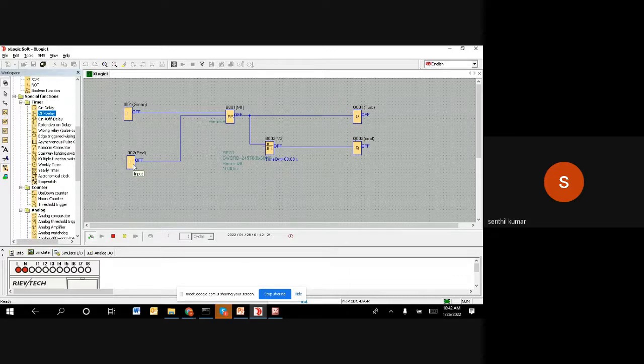Anytime you start the turbine, the cooling system has to go on immediately, whereas when we switch it off, the turbine has to go off immediately, whereas the cooling system has to run for the next predefined time. Based on the design, it can be half an hour, 1 hour, or 2 hours, based on the volume of cooling media required. So that's what it does. You understood some basic knowledge of what this system is inside a power plant. That will give you a positive impression, that you know something. Hope it is clear.